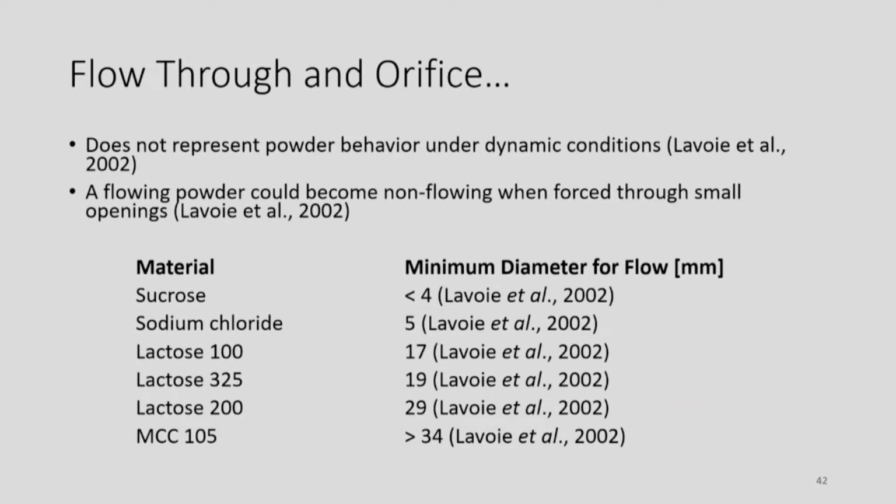This is also a qualitative indicator. Depending on the orifice size, we talked about cohesive arching, mechanical arching, etc., right? Sometimes a free flowing powder might not flow easily through those orifices due to other issues. So when you are using these instruments, make sure you know the powder well before using those values to report, or using them for other calculations.